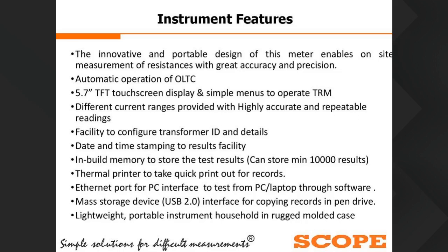Then we have provided a touch screen display and simple menus to operate the instrument. Then facility to configure transformer ID and all transformer details, that is transformer rating, location of the substation, and so on. Then the instrument has different current ranges with highly accurate and repeatable readings.